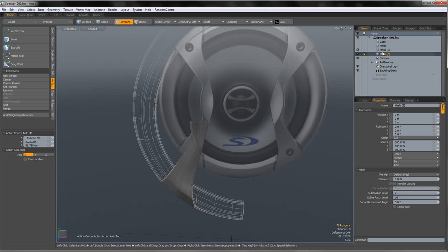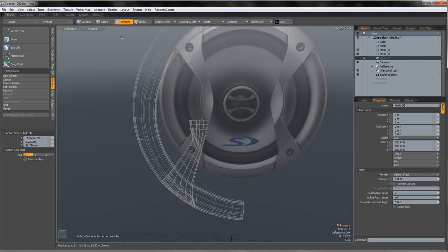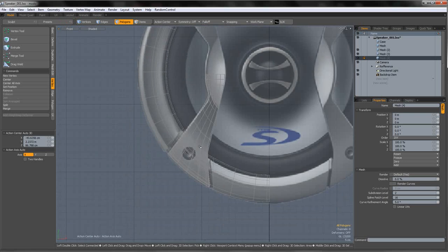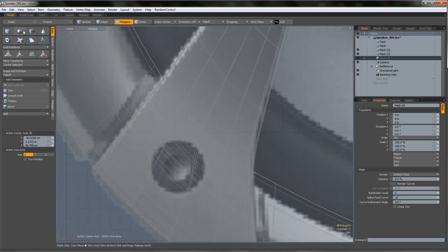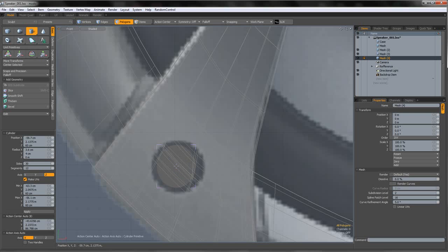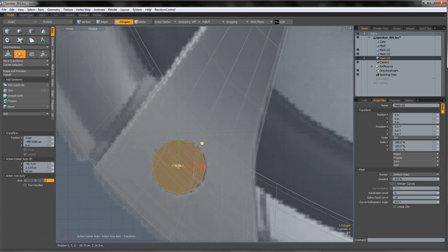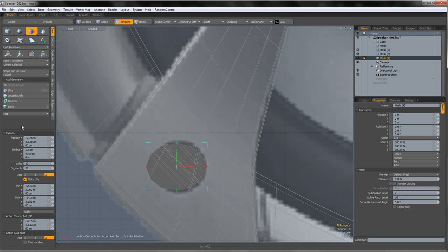And now comes another hard part, and that's drilling the hole for this screw here, which is basically, let's see, 12 sides should be okay, but I don't think I made it round enough, so I'm gonna set 5, 5.